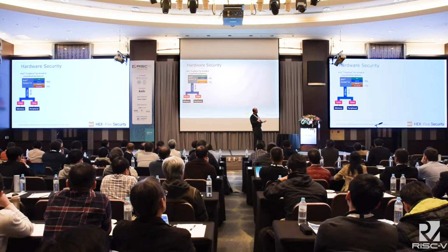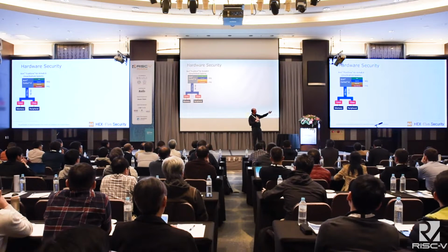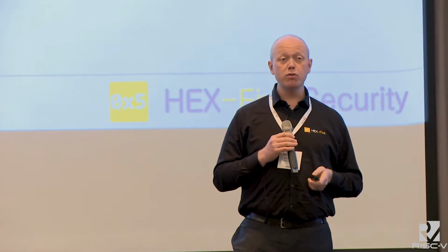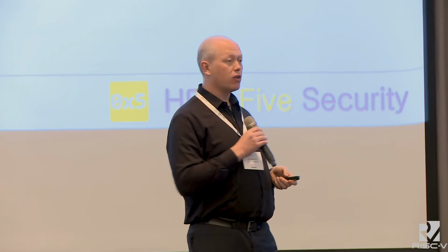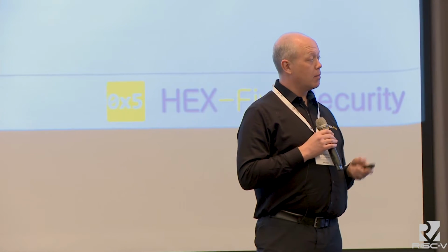You have 2 different kinds of interrupts. You have an IRQ, which is a non-secure world interrupt, and you have an FIQ, which you use for a secure world interrupt. So the challenge here is a couple. We really have 2 domains that are extremely hard-coded in this environment. Once you plug that NS bit, or the modern AXI equivalent of that, you're really sort of stuck with 2 worlds. It's pretty difficult to implement that in a multi-world environment.